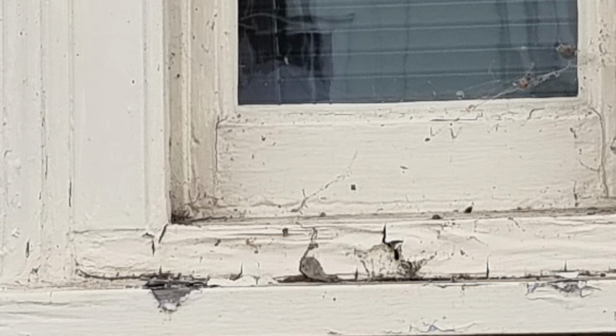Now, that's something you need to get used to looking for because timbers do change in colour. It's a natural material. It'll have colour variation through it anyway. But if you know that particular piece of timber suddenly looks as if it's getting darker, you have to say to yourself, well, is it because it's getting damp? The next thing is that will then lead to staining. It'll lead to peeling paint and so on and so forth. So those are the sort of superficial things to look for.